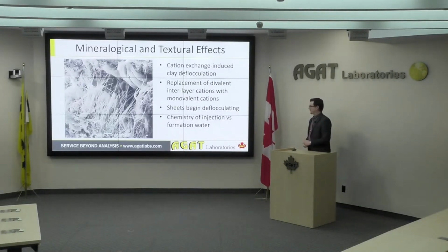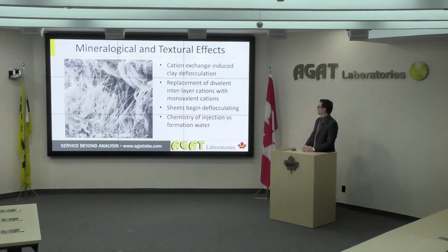We found this very interesting effect that isn't particularly common, but can have a huge impact, and that's a cation exchange induced clay deflocculation. And that's where you have a clay that naturally has a divalent cation in its interlayer space, for instance, calcium, which is 2+. And then you introduce a fluid that is monovalent, like a monovalent brine. So for instance, KCl or NaCl. And the interesting thing was we observed this with KCl, which is typically considered very benign for oil and gas production and completion and testing purposes.